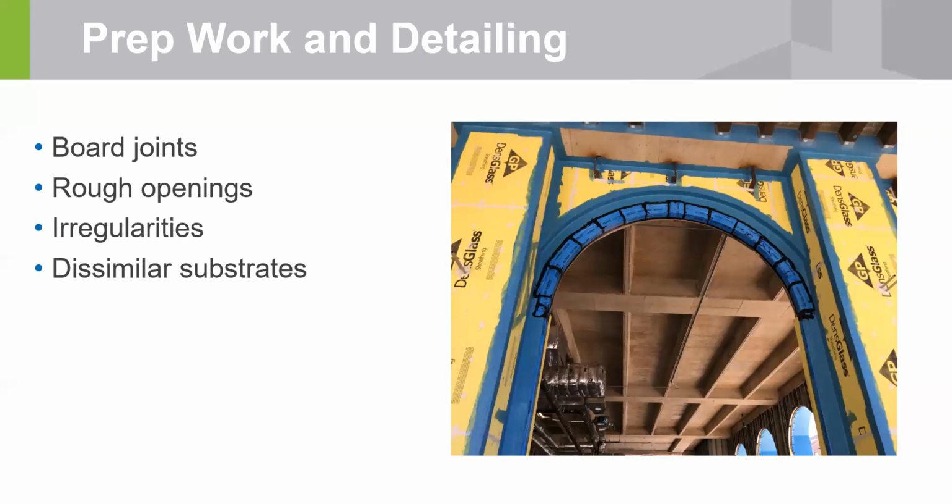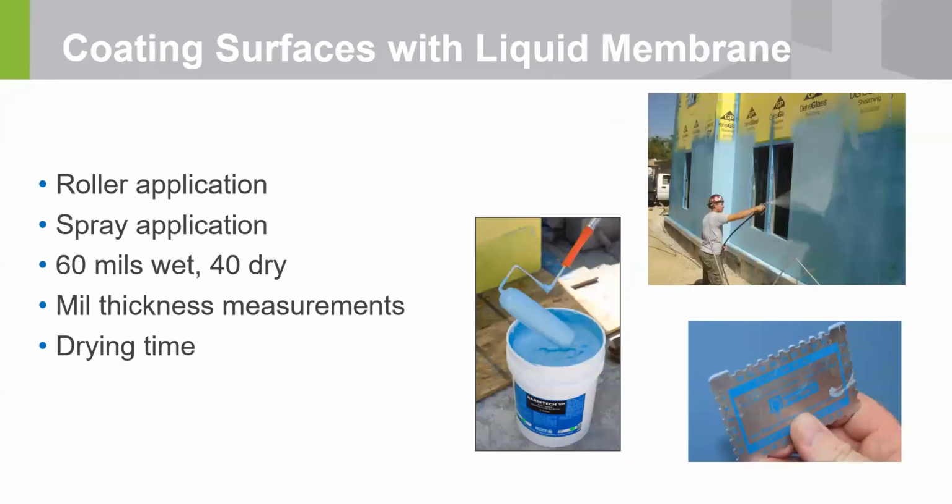So everything there is really nice and buttoned up and airtight, just the way you see it. And then you put that monolithic 40 mil cured coating, and that makes sure that all of it is going to perform as one piece and last once you get the brick up in front of that. Once they did all the detailing, and the detailing, by the way, is about 80% of the labor, coating it on with the spray especially is fast and easy compared to detailing all that stuff.